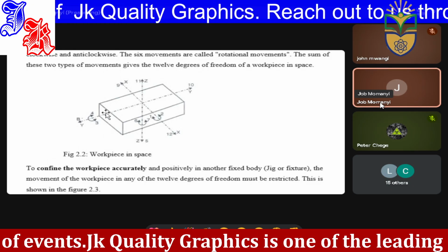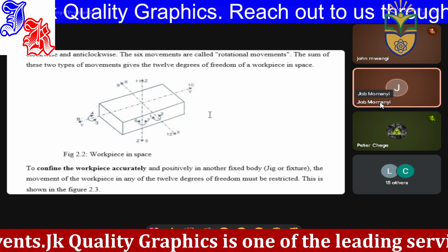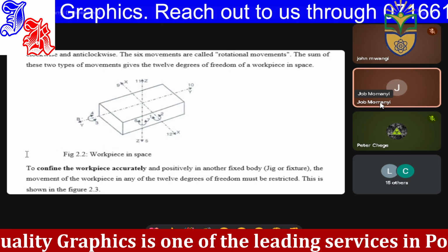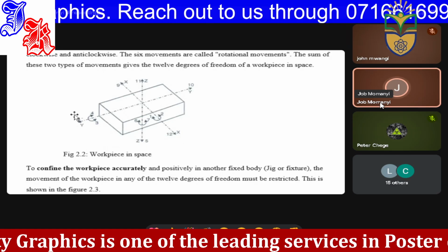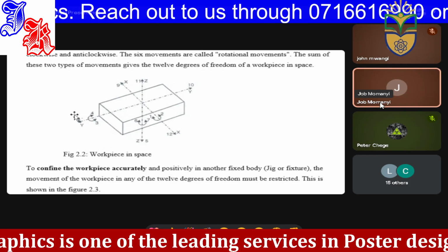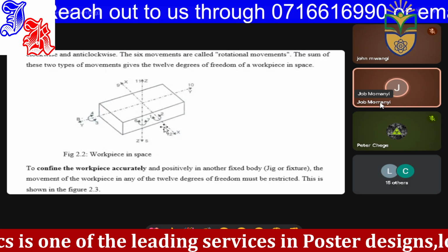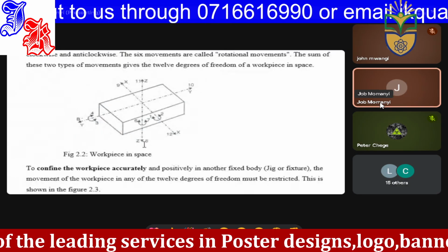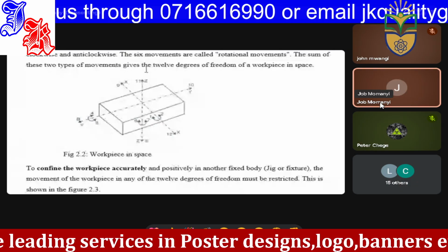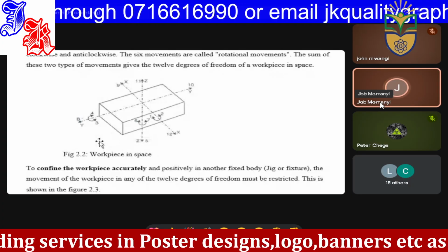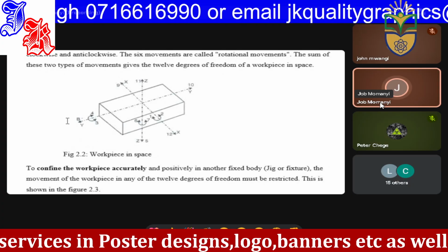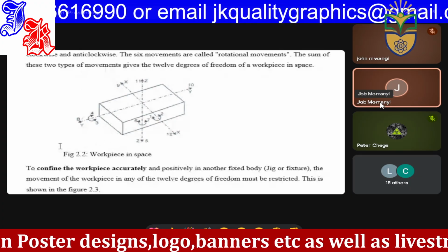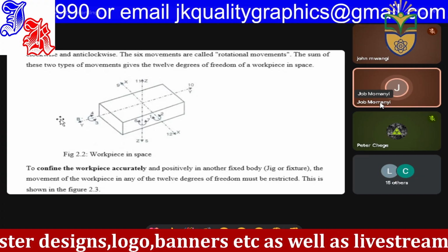So if you don't secure this workpiece, it can move along the Y, that is 1 degree of movement, along the X, along the Z, and also you can rotate this workpiece around all the axes.